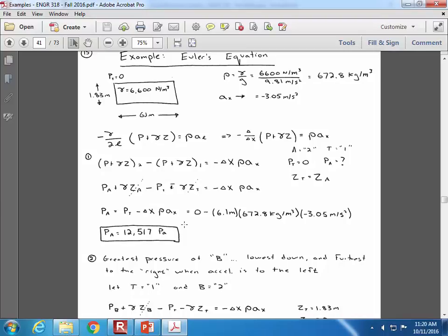Simply because the acceleration, remember, is along the horizontal axis. So in the x direction, B is further to the right. And this is another point of occasional confusion and mistakes for students. They're thinking, well, location T is higher, so shouldn't that be 2 compared to B? But our acceleration is side to side here. It's not up and down. Although, of course, gravity still applies here. This truck is driving down the road. It's not floating through outer space. So even though gravity applies, location B still is further to the right than location T. So that's why I've said T is 1 and B is 2.